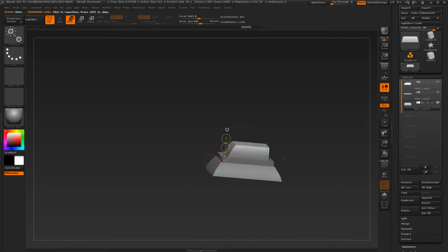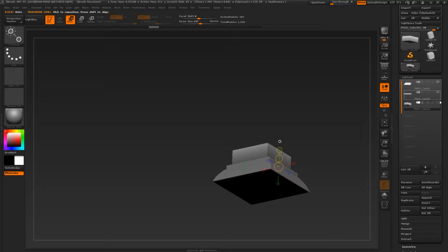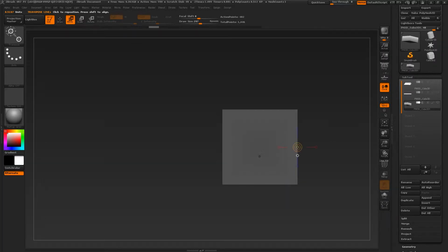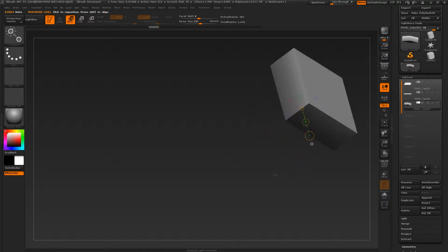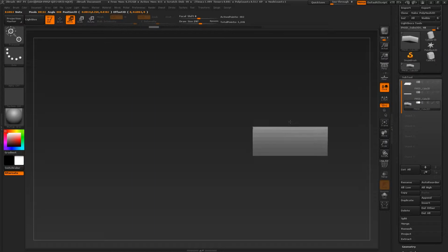If you want to scale everything generally, what you can do is, from the top view, create a line with a Transpose Master, and then in a side view, click on the line that's going in the direction we want. In this case, we want to create a line going upwards, so we click on the line pointing upwards in the Transpose Master.